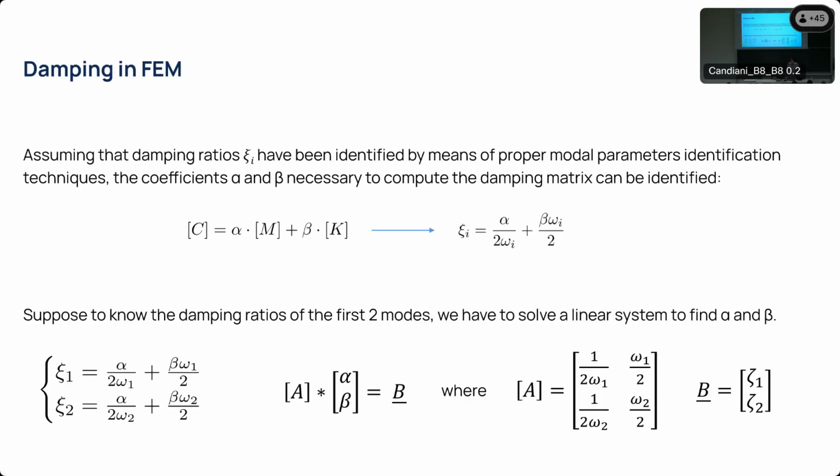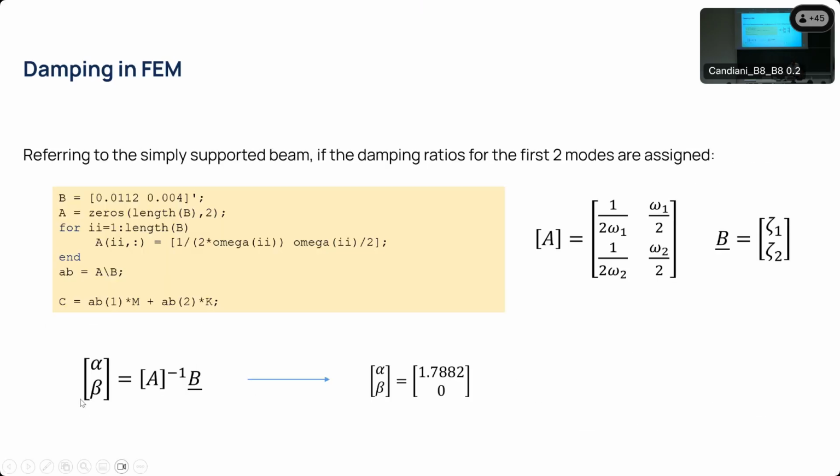little better. So again, damping ratios, minimization of the problem, you create the matrix, you extract the parameters, and then you are able to write the damping matrix as the weighted sum of matrix K and matrix M. So this works basically kind of flawlessly. Remember that in your assignment you will receive, if I'm not mistaken, you will already have the values of coefficients alpha and beta or of the various mode shapes of the structure. So you can obtain those parameters, and then you can create the damping matrix of your structure. So solving a linear system, finding parameters, summing them, and creating the damping matrix.